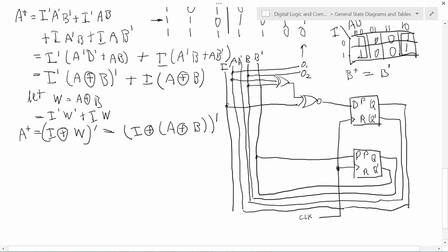And then we can reset to state 0. We don't necessarily have to start in state 0; we can reset to a different state if we wanted to. But for the purposes of this video, we're just going to start in state 0, which means we can connect the R signals from both flip-flops to the reset signal.